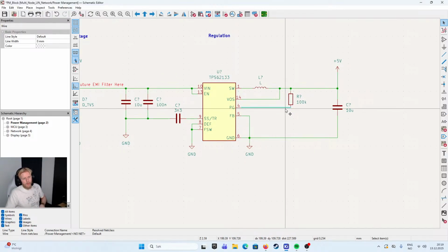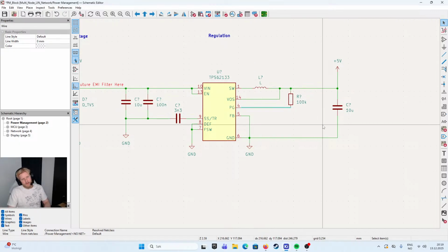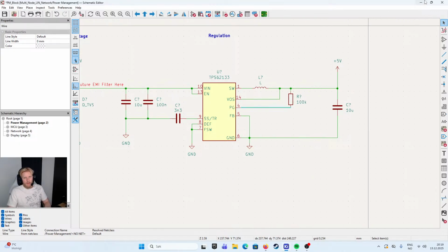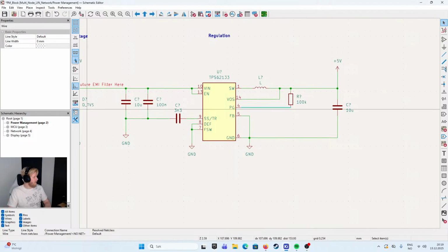So this could be used to give the signal to the next regulator, for example, to start, or something else, I guess. It's crucial for ensuring downstream components receive reliable power, preventing errors by delaying processor or peripheral power up until the DC-DC is ready, and can be used with GPIOs or LEDs to monitor power health.